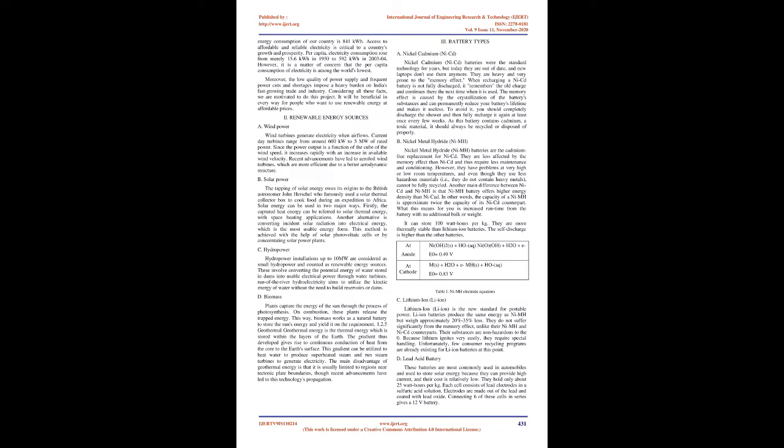The grid-connected systems feed the electricity produced by solar panels to the grid using an inverter. When the electricity is needed during the night or periods with little sunlight, the energy is taken back from the grid. In off-grid systems, normally the excess electricity is stored in batteries during the daytime, and the batteries are used to power the consumer appliances at times when photovoltaic panels do not have enough energy. Solar charge controllers play a vital role in isolated solar systems. Their goal is to ensure that the batteries are working in optimal conditions, mainly to prevent overcharging, by disconnecting solar panels when batteries are full, and deep discharge, by disconnecting the load when necessary.